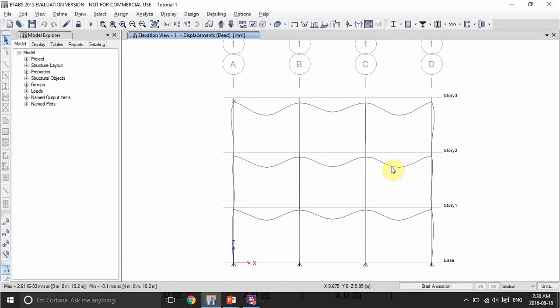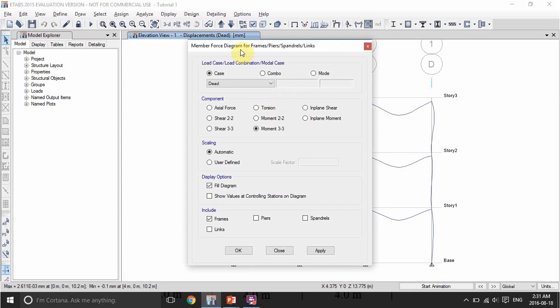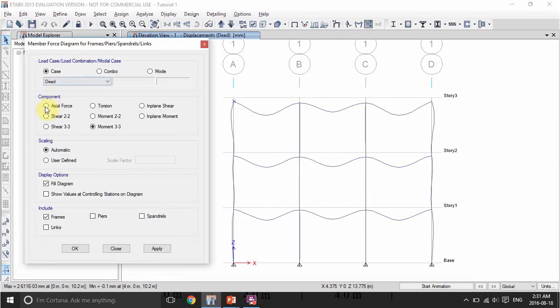Of course, inside the beam here, we don't have any joints defined, therefore we can't get the actual values, but I will show you a trick later on how to get these values. But you can get the values of the deformations now on the nodes. Now to see the straining actions here, let's say we want to see the axial force due to the load combination 1.4 dead with the values.